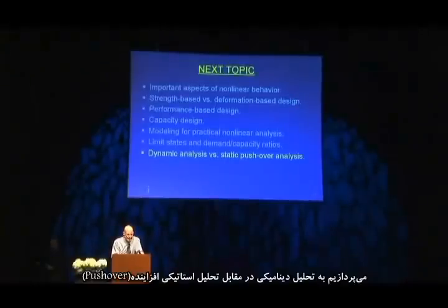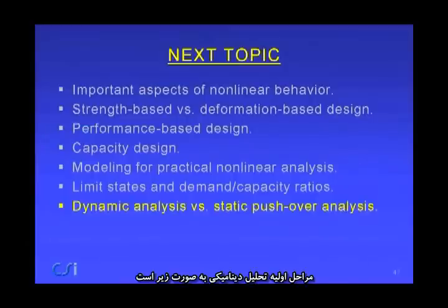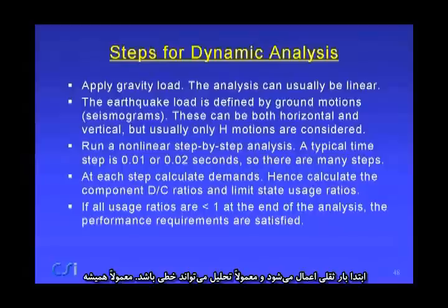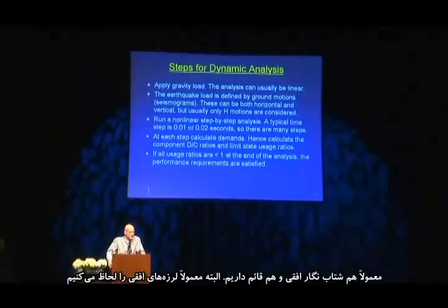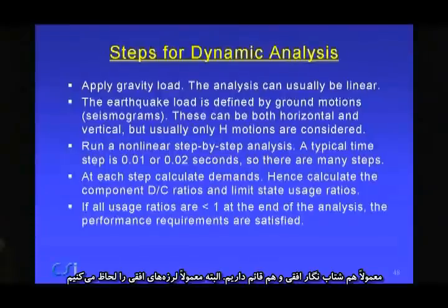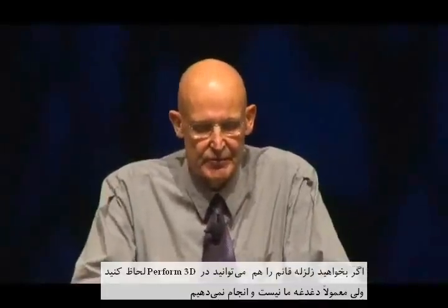Next topic, let's look at dynamic analysis versus static pushover, briefly. Dynamic analysis first, the steps are as follows. Apply the gravity load first. Usually the analysis can be linear, not always, but usually. The earthquake load is defined by ground motion, seismograms or accelerograms. Typically you'll have both horizontal and vertical seismograms. Usually you'll only consider the horizontal motions. You can consider vertical motions in Perform 3D if you like, but it opens up all sorts of cans of worms, and usually we don't.